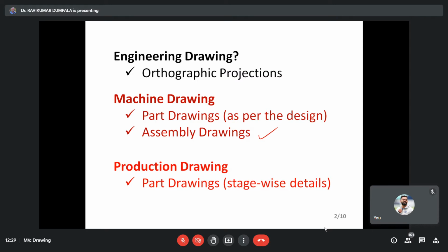Most engineering components, just before the final stages or in between, go for heat treatment also. At the initial stages, the material is in annealed condition, so you will not have that many properties. You might have studied this in metallurgy. Initially we don't do heat treatment. Why? Because machining would be very complex, as you are going to remove most of the material. Then you heat treat to increase the hardness and strength. Then you go for finishing processes like hard turning, grinding operations, and any other polishing operations.